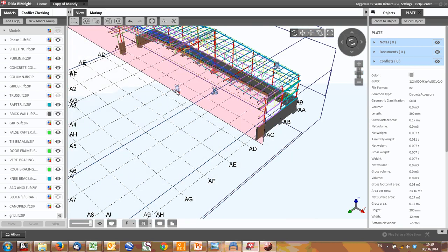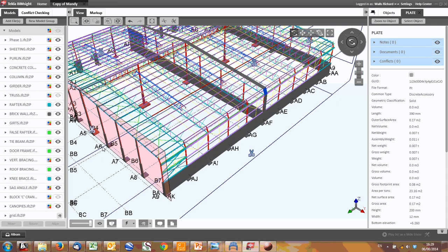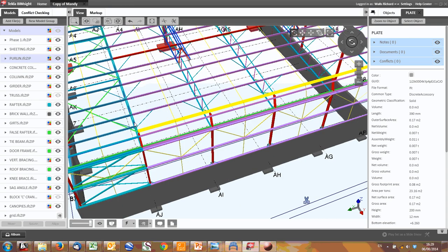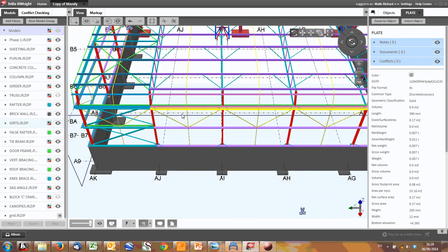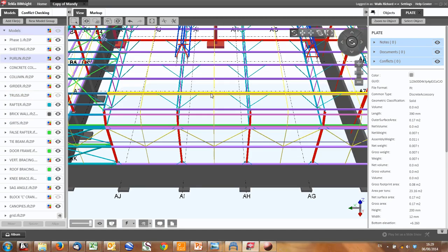And to come back. And the number of bays, if I come through here and pull this building out, the number of bays is governed a bit by selection. First, and by bay I mean the distance from column to column. Normally this is between sort of 5 and 7.5 meters. On bigger buildings it might go to 9, even 12 meters, but it just means you have very big purlins and girts.